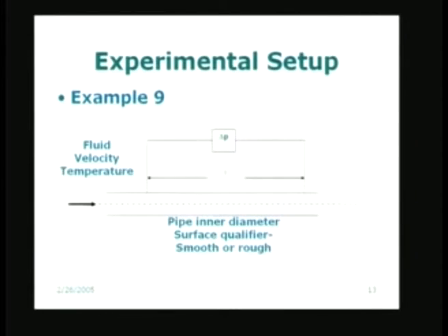But in general, when we are measuring the friction factor, we would like to have isothermal flow conditions. That means that the flow is at one single temperature. We identify a certain length of the pipe or the tube as is shown here, and that is the length L, and I am going to put a pressure measuring or differential pressure transducer or differential pressure measuring instrument, and I will get this delta P. This is the outcome of the experiment.